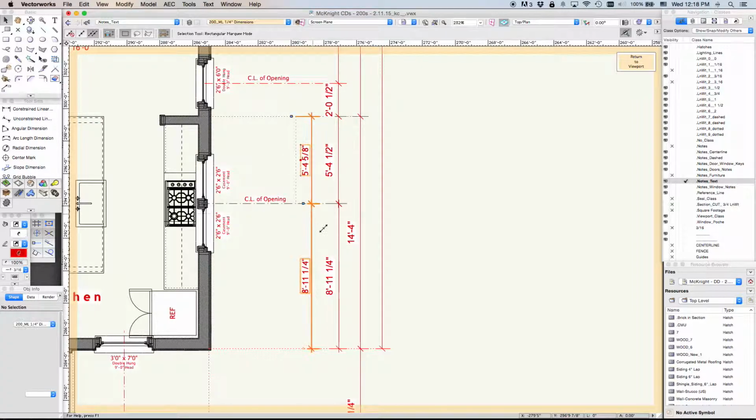Here's a good example. I try not to get down to 1/8 inch dimensions so that the framers aren't talking trash about me in the field. In commercial work it's more common. In residential work it's kind of a joke. Usually 1/4 inch is about as fine a detail as you get, with rough framing especially.